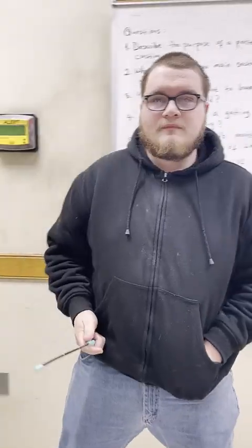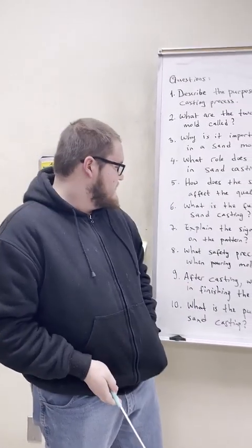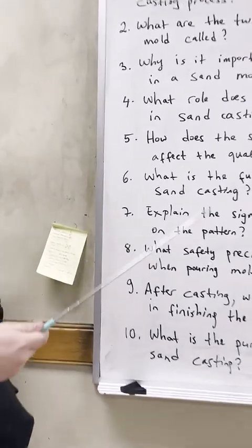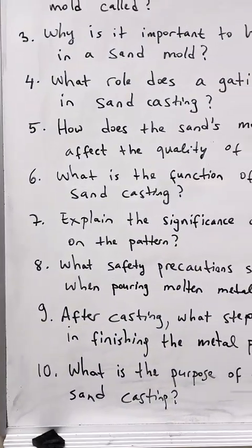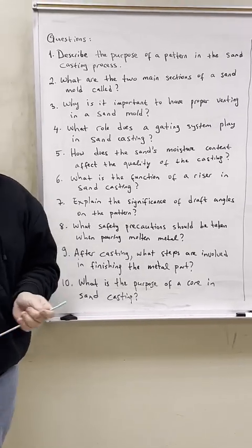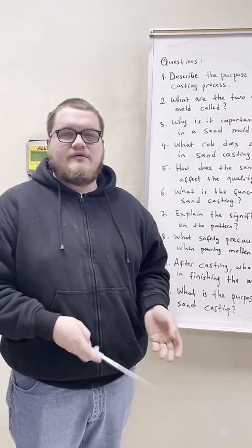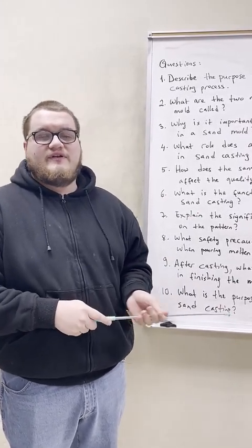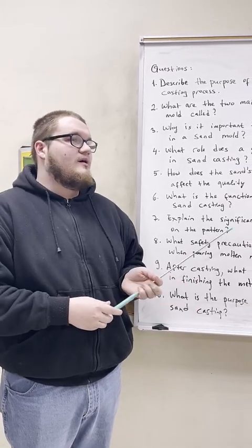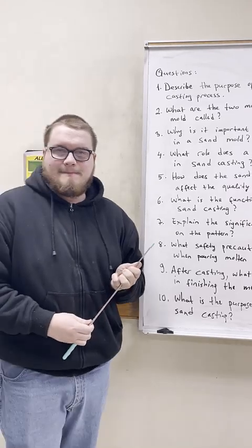Thank you. My name is Lucas Posey. My question was number 7, to explain the significance of draft angles on the pattern. Basically, the draft angles are important so that the pattern can be safely lifted out without rubbing up against the sand and causing damage to it.